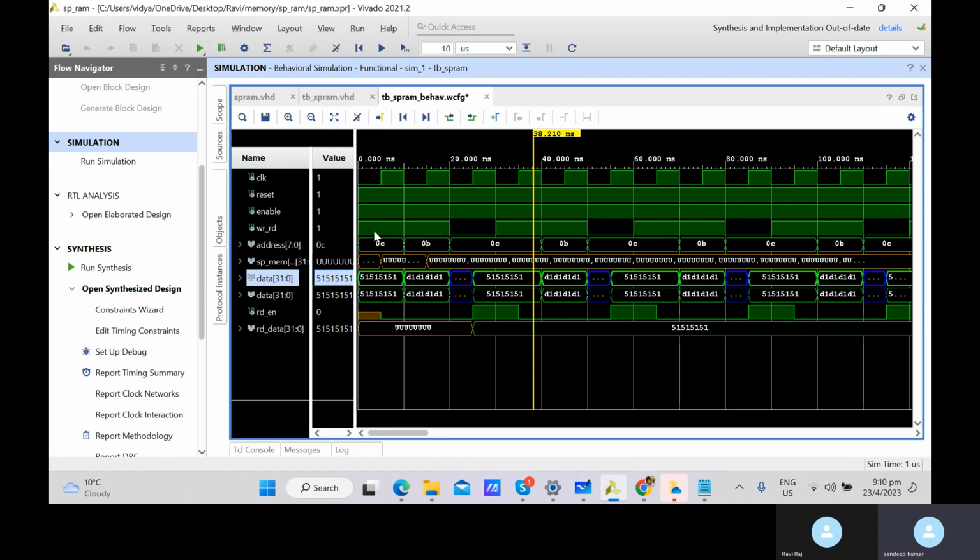So here we are writing, and read. So we are writing write data. We are driving the data whenever there's a write, and otherwise this guy is driving Z. On the data bus you'll be seeing this guy driving Z. Whenever read enable is not there, it will drive Z on the data, so that the test bench can drive it.